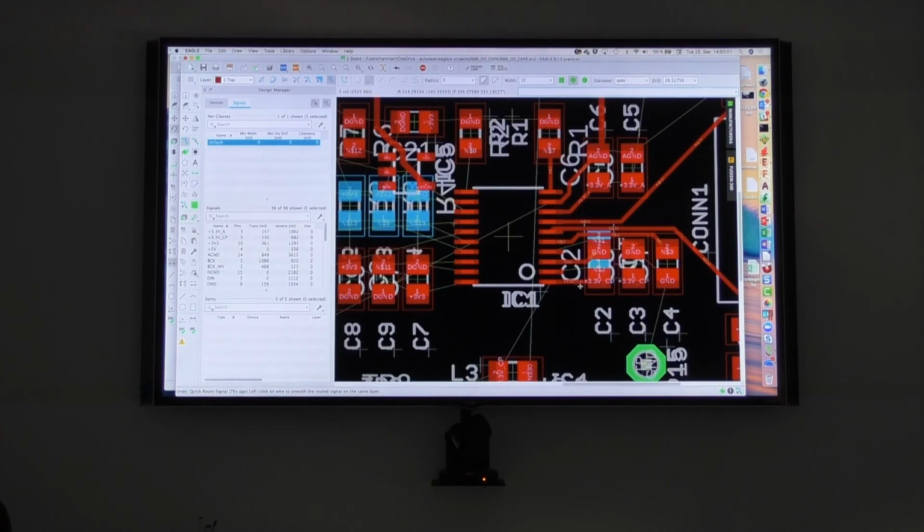If I look at this, it's not very nice. It might work, but you have to think about how to place the components, how is the way of my signal, where do I put it. I have to take care of different signals. I have high current, high frequency, some impedance stuff. I can't simply mix this all together.